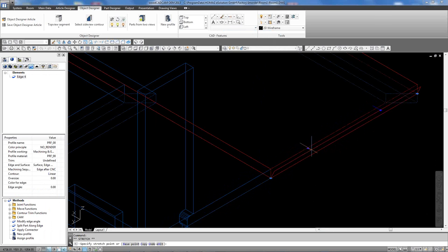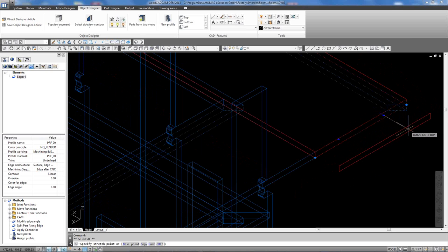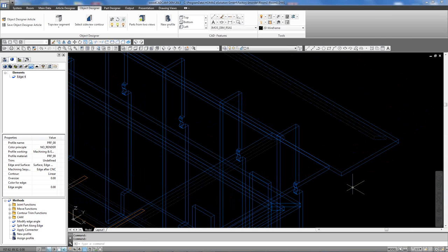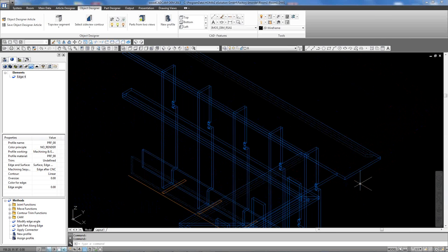All right, now I'm going to grab this little angle so we can see here that I'm putting a bevel on that edge now, right? Oh, okay. Yeah. And then the lollipop will let you change the size of it if I wanted to extend this part out 3 inches. Could do that. Okay. So that's really handy with 3D workings, and that'll work on any part, whether it's a cabinet, a die wall, a countertop, whatever the heck it is. In 3D, you can make any changes like that.